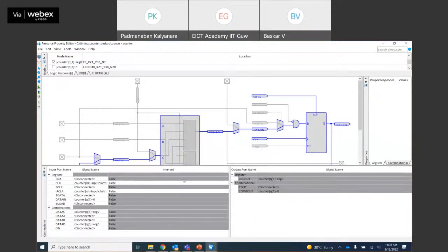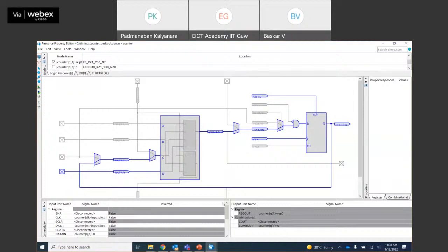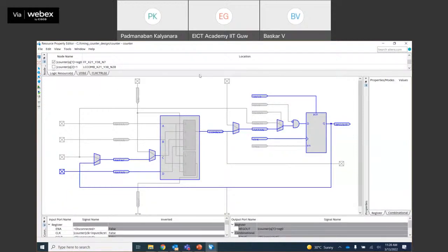It shows the start, and it goes through the combo logic. All the information we could see for a specific path. In detail, you can get multiple pieces of information for each and every register, from where it starts, how it goes, and then ends at the data pin of the flip-flop.